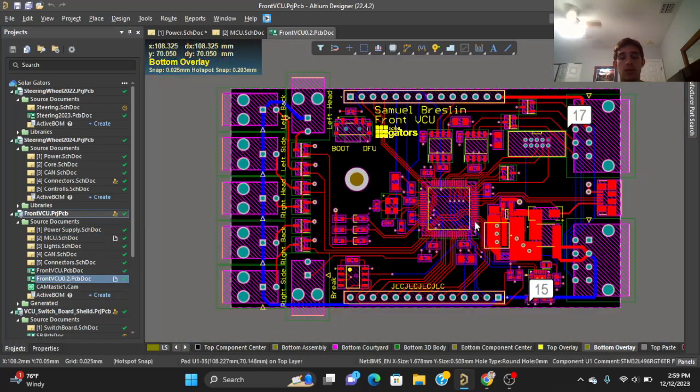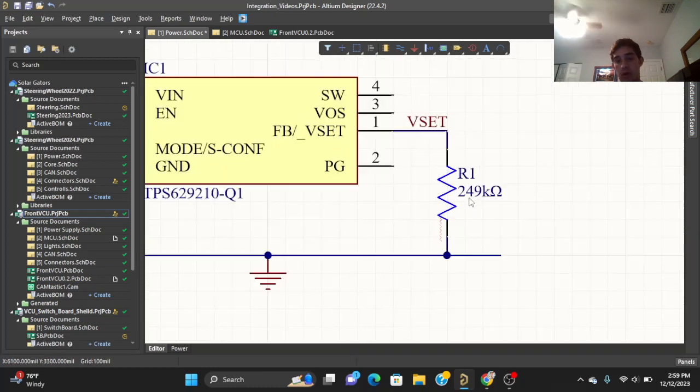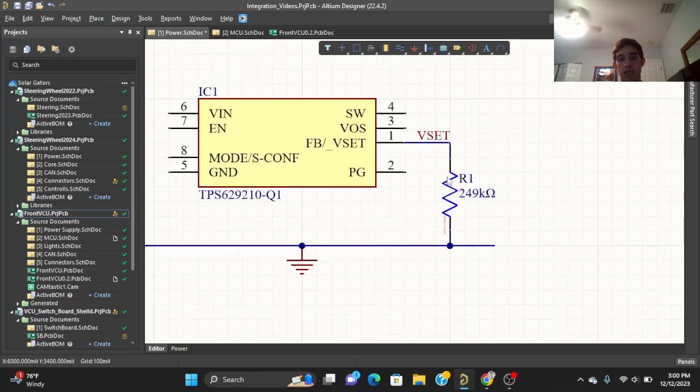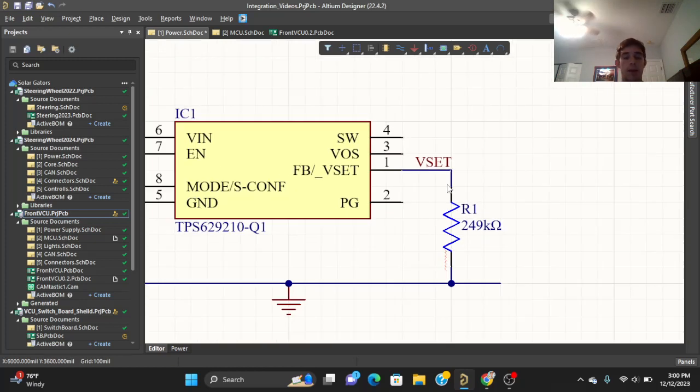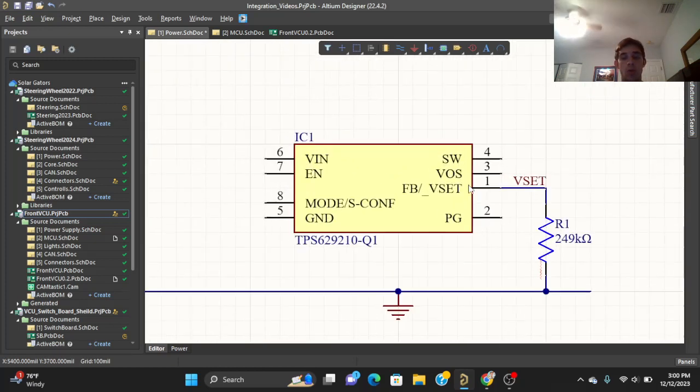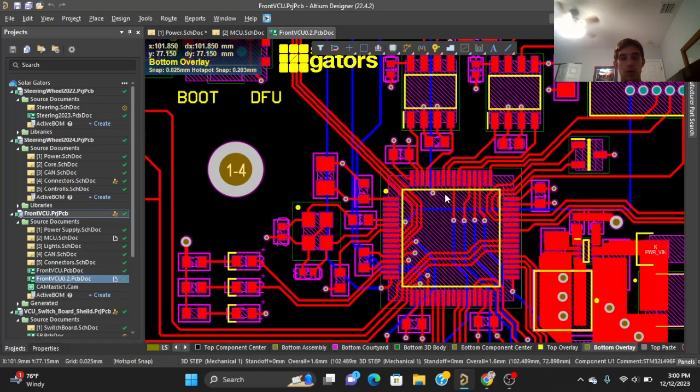Now this is the main use of net labels, but there is one other smaller use, and this is essentially good practice. Without this net label, Altium doesn't really know what this wire should be called when you go to route things up in your PCB design.